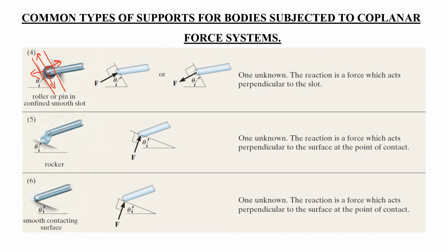Now if you try and pull it outwards, this applies a force in this direction because of this rail, and if you try and push it here, this roller applies a force in the upward direction. But again, if you apply a force here or here, this roller cannot do anything because it is a roller and it is designed to move freely.